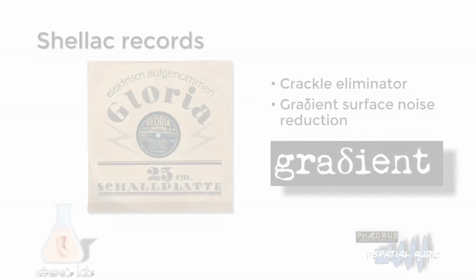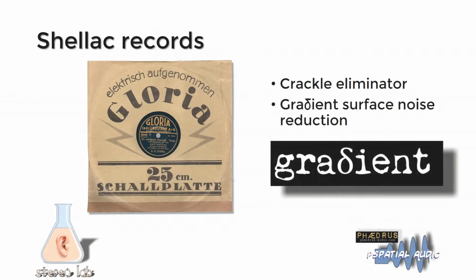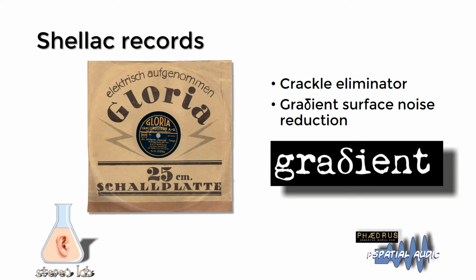Stereolab also includes unique processing for 78s, or more correctly, Shellac era records. For example, Gradient is a unique noise reduction process for Shellac era needle drops, included for the first time in Stereolab. The development of Gradient followed much experimental work on Fourier-based noise removal, all of which proved pretty disappointing. Although transform-based noise reduction produces noticeable and worthwhile improvement in the noise, it also introduces unpleasant audio artifacts which include birdies and a hollow ringing quality to the program.